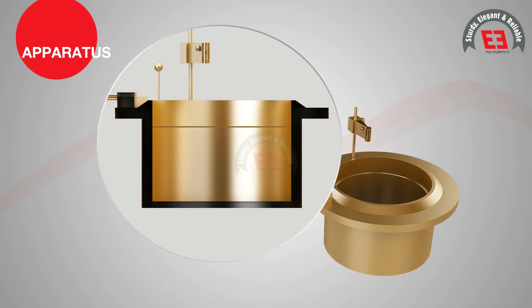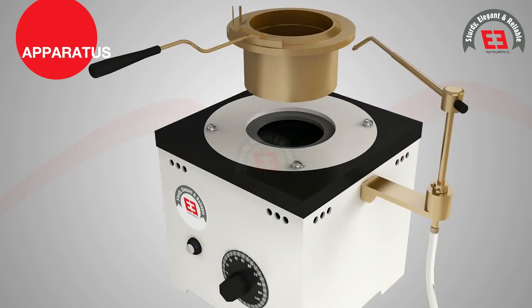The filling mark is between 9 mm to 10 mm from the top of the cup. The inside height of the cup is between 32.5 mm to 34 mm. The heating plate is of sufficient dimensions and material to ensure that the thermal heat to the test cup is only applied to the bottom of the test cup. The heater is controlled by suitable energy regulator.